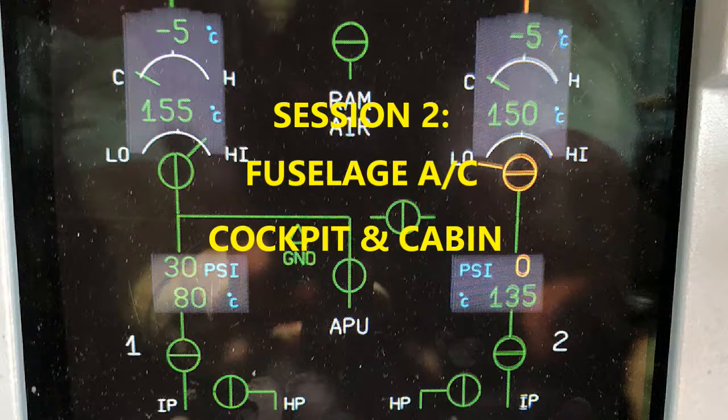You also have air that's going to get through so that it can cool the bearing, and then all that gets discharged into the ram airflow. So there's a system there just to make sure you've got the cooling going on for those bearings. And of course you have some seals there just to prevent leakage, etc. And then you have the fan air from this air cycle machine that's going to be discharged through a nozzle, and that's just a fact. And then the primary heat exchanger outlet is connected to the discharge ram airflow through a diffuser.